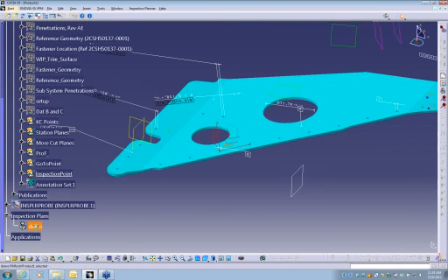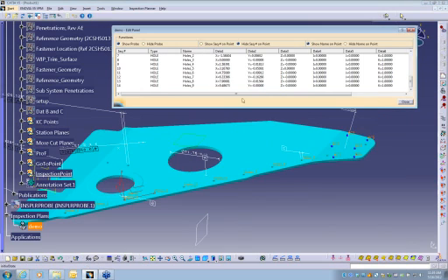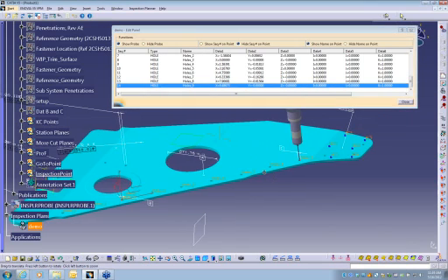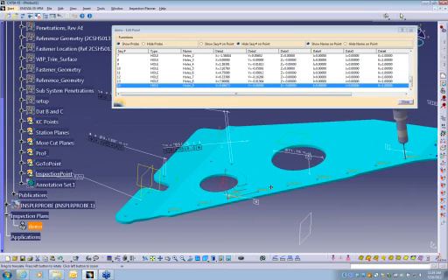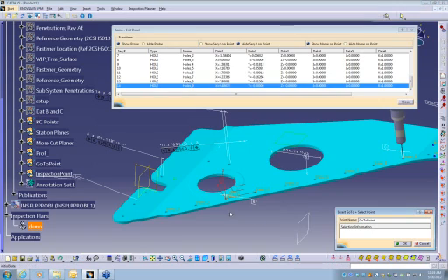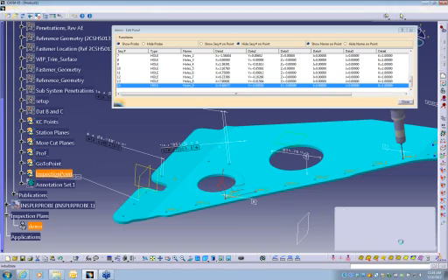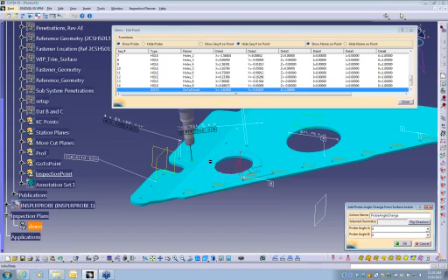So we'll go back into our plan. We'll demonstrate some more ways to create inspection. Now let's say that we wanted to put a grid on this surface right here. We already have this go-to point, so I don't have to create another go-to point. I can come over here. If I wanted to align the probe to that surface, I could pick one of our probe change icons.